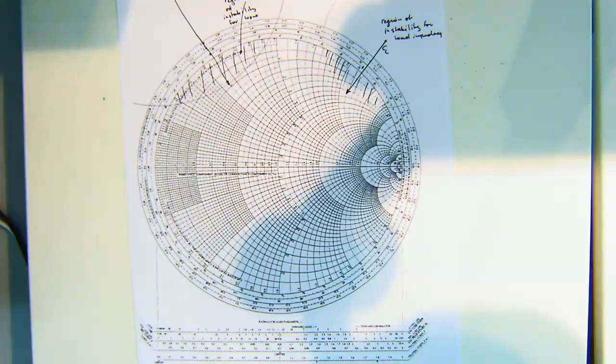That's all that is, in a practical design. When you grab a resistor or an inductor, you'll realise they're never exact. Even though they say 1 millihenry plus or minus 10%, or a resistance of 101 ohms plus or minus 10%, or 1%, or 0.1%, depending on the type of resistor you've chosen, right?